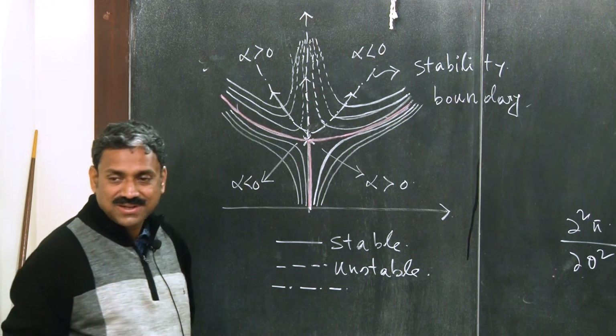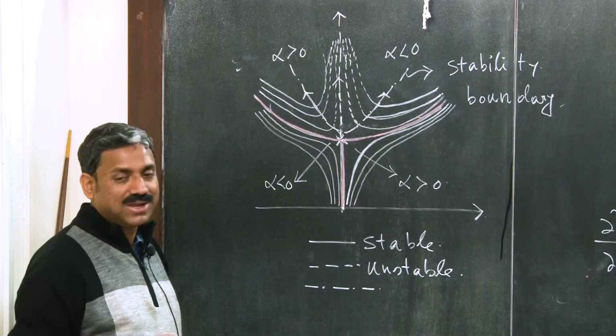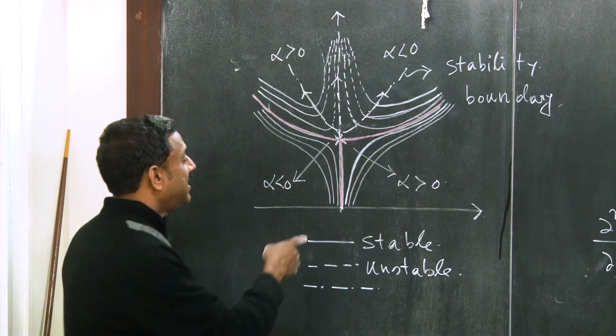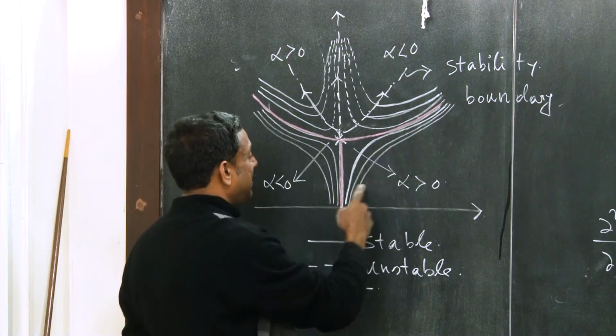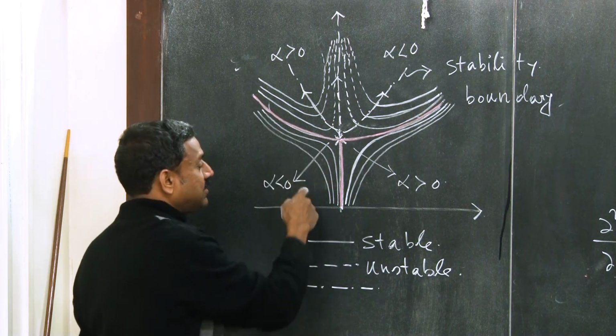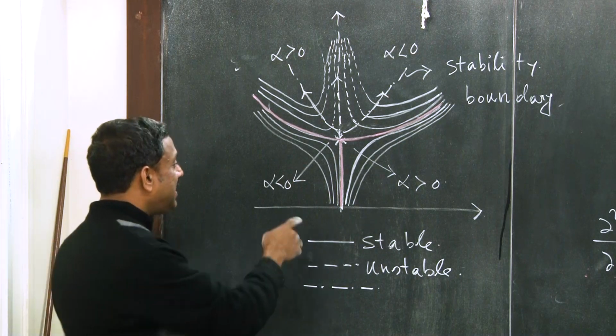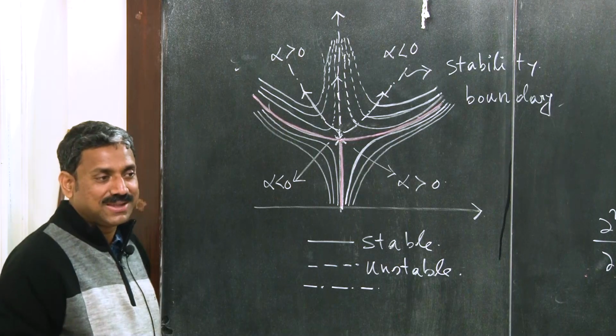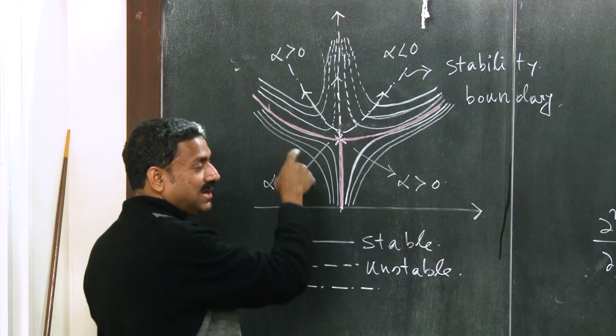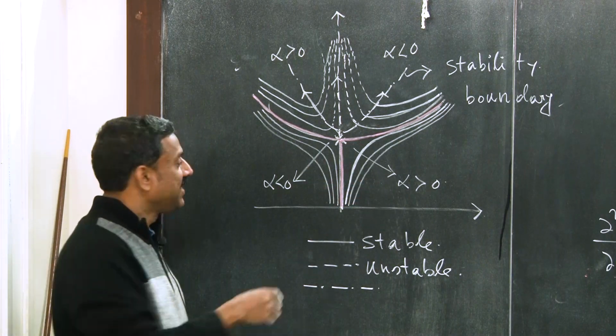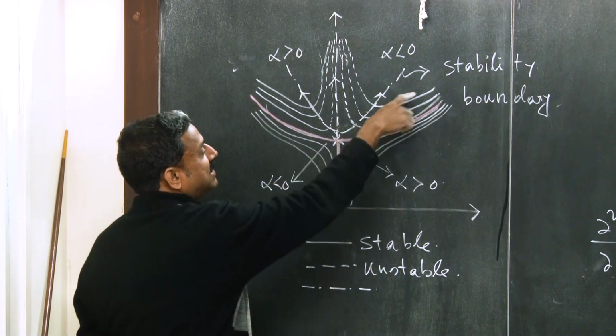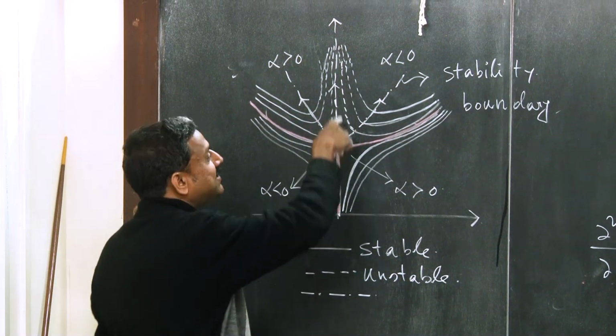If it's a multi-dimensional space, a multi-degree freedom system, you have to take, of course, the determinant and principal minor. Positive means it's stable; these are all stable. See, in negative, for negative theta, the slope will be negative. So ultimately del p del theta is positive. So that's why it is positive. There it is positive, here it is negative. That's why it is unstable.